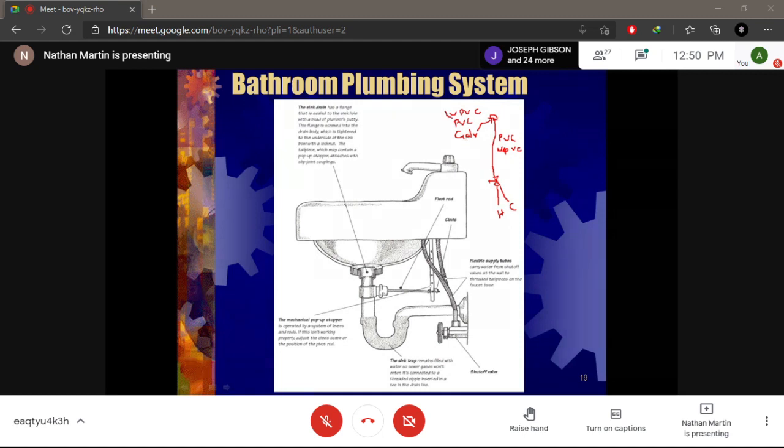Matthew, right? So we are saying that if we were to use this, after a period of time the threading will go. Then you have to dig out your bathroom or whatever. If it's a shower that is frequently used, like in a shower room for a gym, then after a time the threading here will be damaged because of the expansion and contraction of the fitting, and then it will burst, and then you have to dig out the wall. While this, being galvanized, is able to handle the expansion and contraction based on the hot water coming out or lukewarm water. All right.